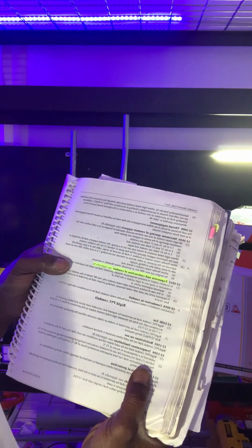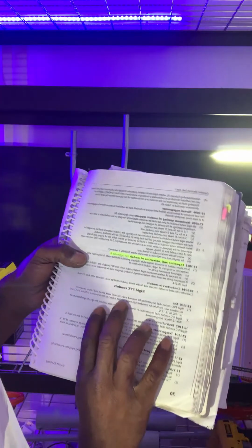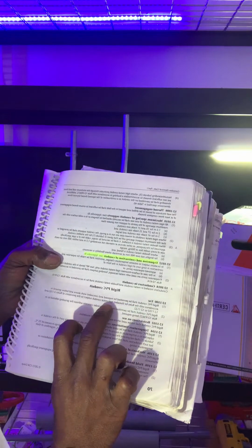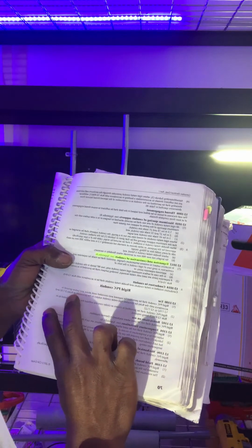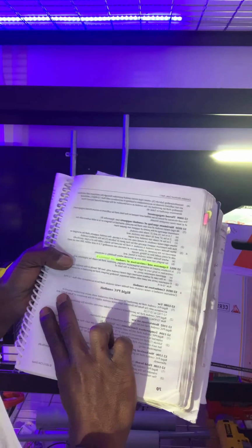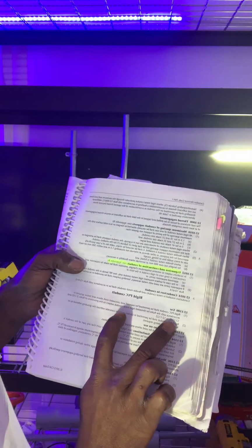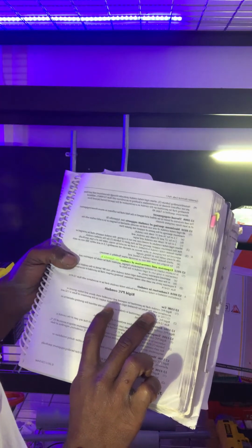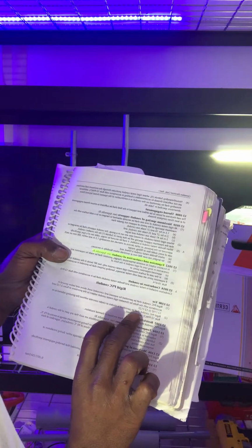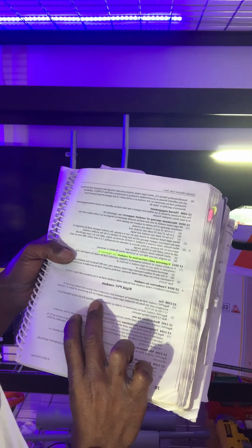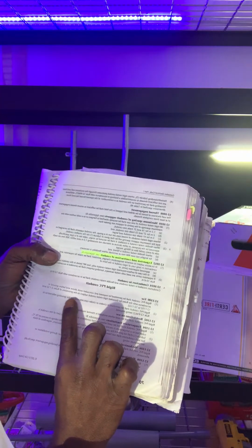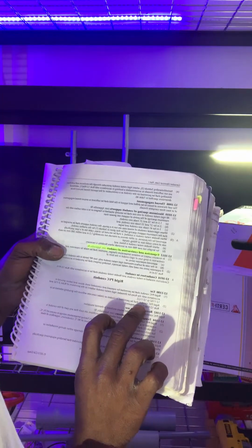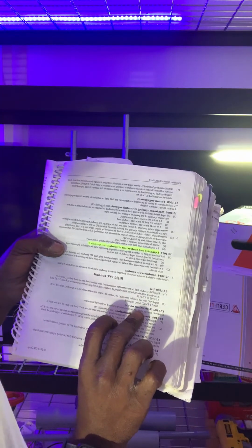12-1100. Rigid PVC conduit shall be permitted for exposed and concealed work above and below ground in accordance with the rules for threaded rigid metal conduit, subject to the provision of Rules 2-132 and 12-1102 to 12-1122. Rigid PVC conduit shall be permitted in cinders or cinder concrete without the grouting referred to in Rule 12-936 being required.